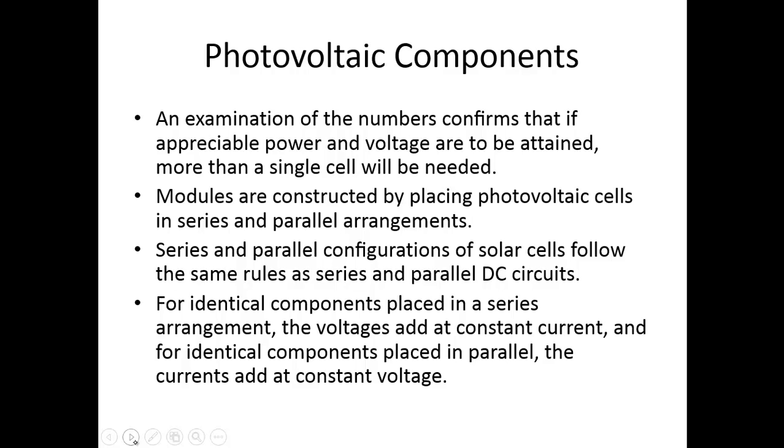Series and parallel configurations of solar cells follow the same rules as series and parallel DC circuits. For identical components placed in a series arrangement, the voltages add at constant current, and for identical components placed in parallel, the currents add at constant voltage.